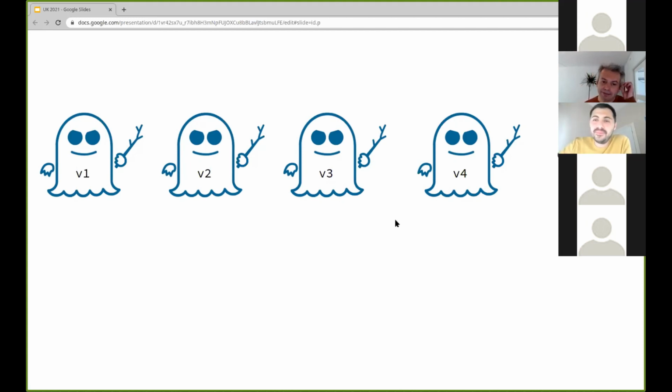I think there is a main difference in the semantics. They have an explicit reorder buffer, and we don't have an explicit reorder buffer. This allows us to be slightly more abstract. For example, we allow some additional reorder behavior: we allow stores to different addresses to be executed in any order, while the stores in that work satisfy a total store order. That means the stores are totally ordered when they are sent to the memory, and this is not always the case on a modern processor.